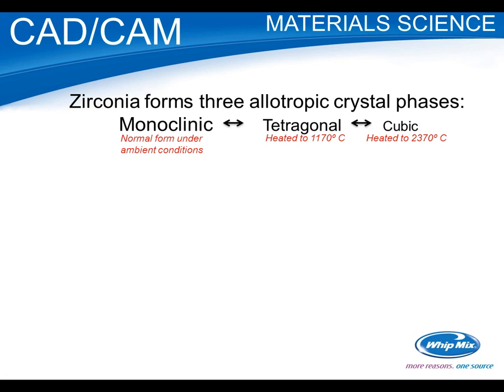And basically, the atoms are realigning and kind of scrunching in a little tighter. So when it's heated above 1170, we have this tighter configuration. And I don't know if it's obvious to you, but if you notice my font size from monoclinic to tetragonal to cubic gets smaller. All right? So as it's heated and takes on this other structural form or cubic form, it's really kind of shrinking in size, getting denser. And then if you heat it further, you'll get to the cubic. That would be what we consider the cubic zirconia.